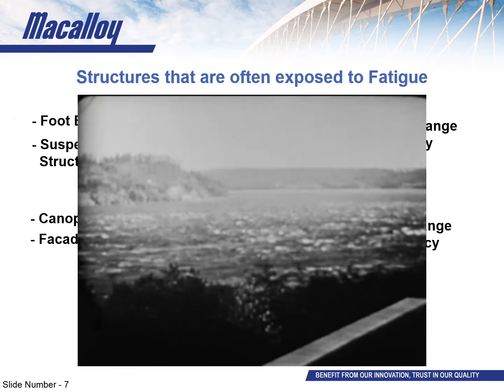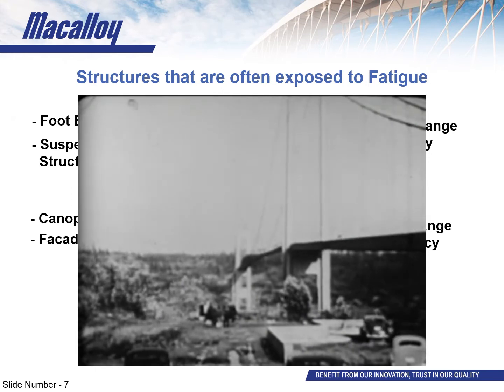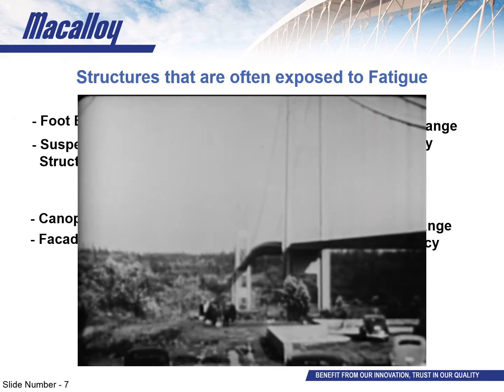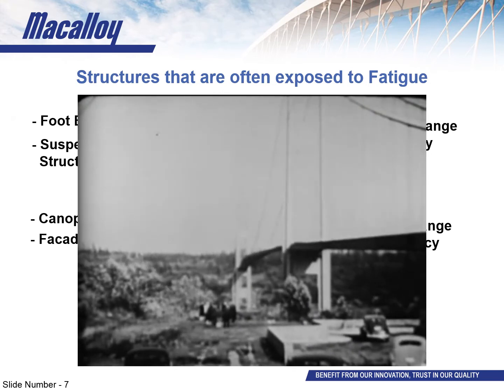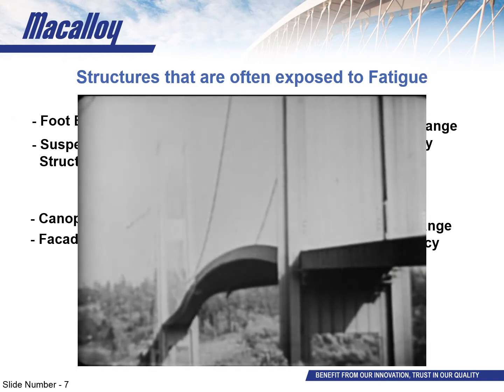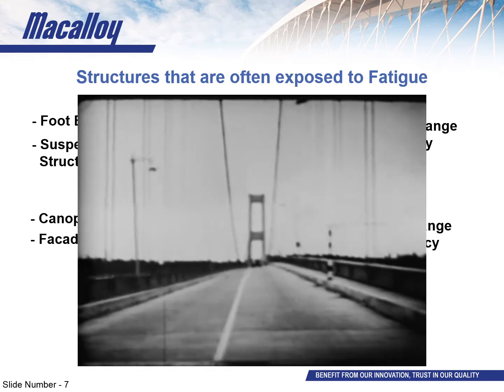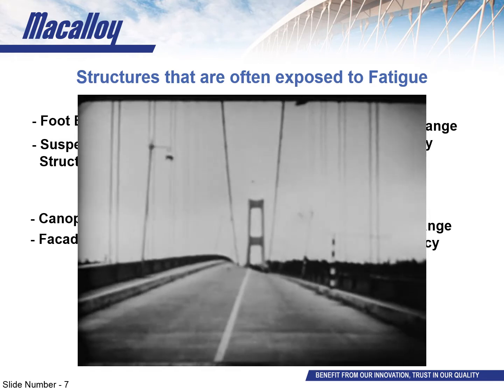I imagine a lot of you have heard of the Tacoma Narrows Bridge, informally known as Galloping Gertie. Now, this is an example of where the frequency of the cyclic loading actually matched up with the natural frequency of the structure itself. So those two forces accumulate into the phenomenon that's known as resonance. Now, this results in much larger stress ranges, higher frequencies, and an expedited fatigue failure.